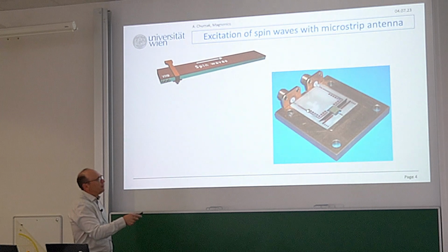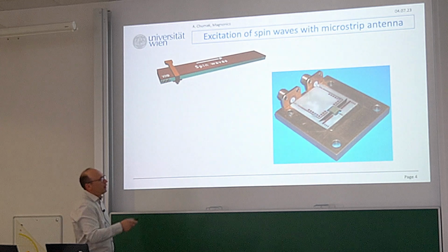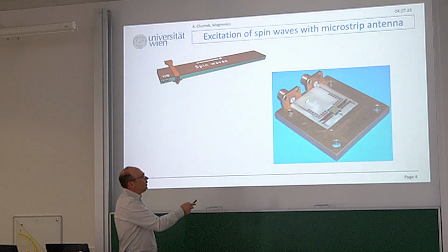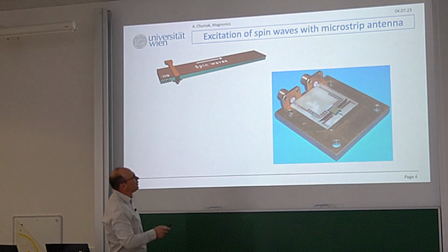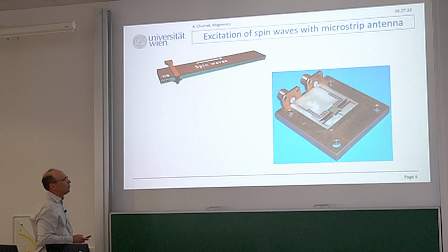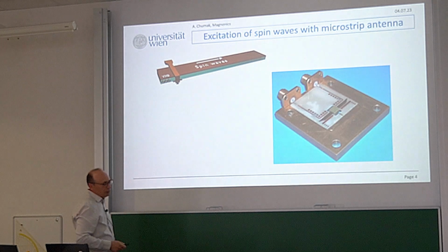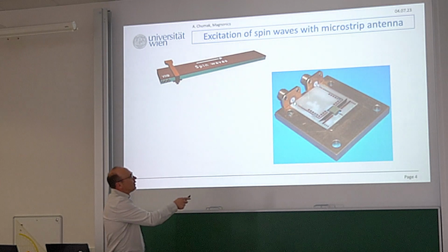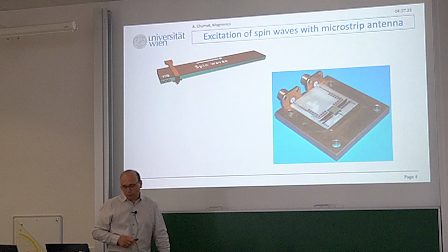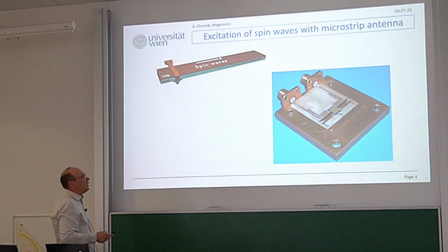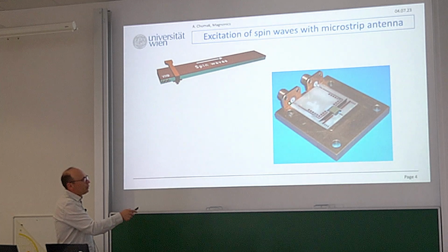This is a 50 ohm characteristic impedance microstrip line, so it's metallized at the bottom. This material looks a bit transparent, so it could be aluminum oxide, alumina, or pretty often people use simple Duroid for microstrip lines. Then you have a 50 ohm matched line, and here it was soldered to a coaxial line, which is also 50 ohm matched. Nowadays we pretty often use so-called end-launch connectors, where you clamp mechanically, which also works quite well. And the connectors can be magnetic or non-magnetic, depending on what you need.